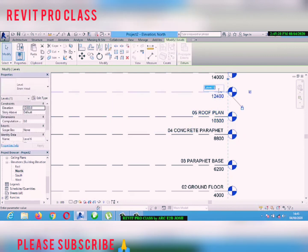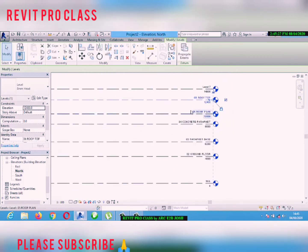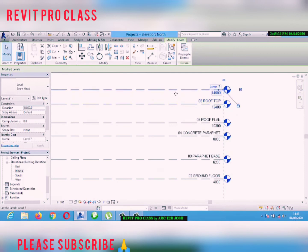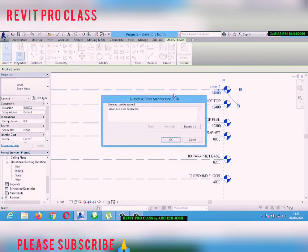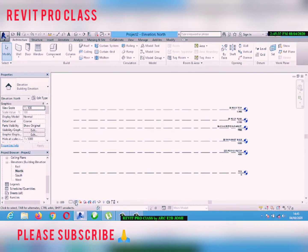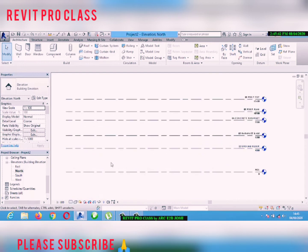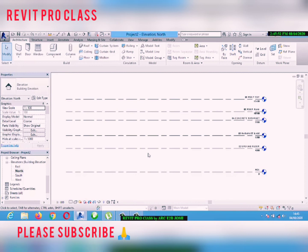Then level 6, 06 rooftop, because of course you're going to view the whole building from the top, so we don't need this level 7. I'll tell you why as we get further. Okay, so this is it. After you've succeeded in naming your levels, the next thing to do is to dimension your levels.